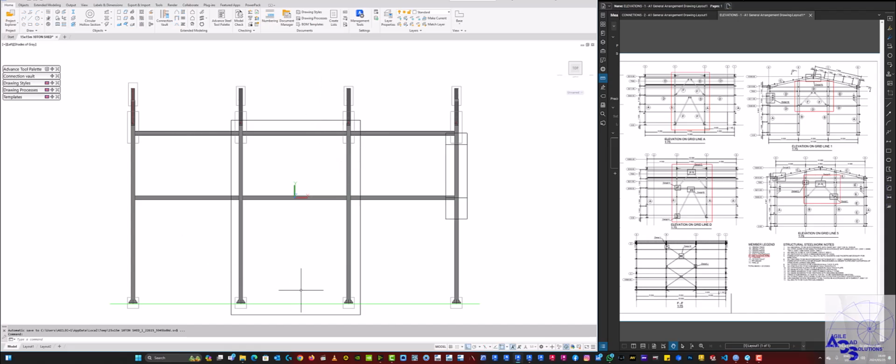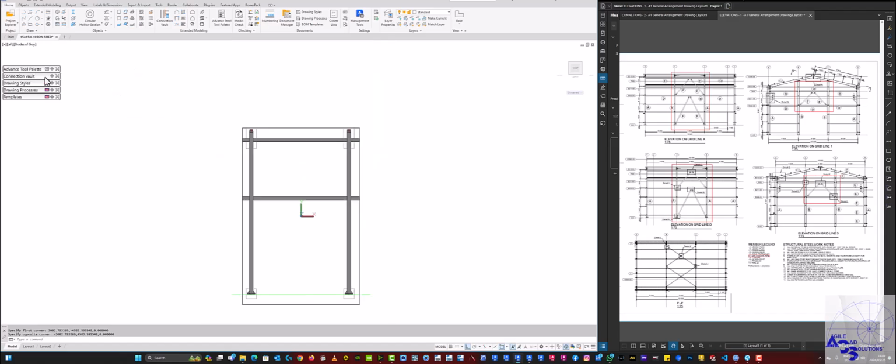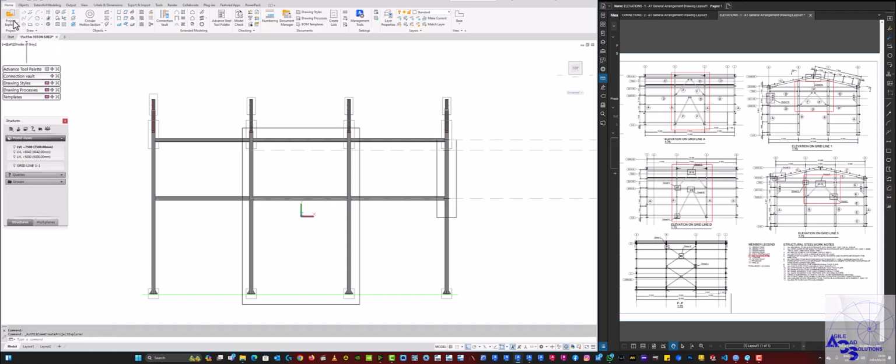So how do I then only see my elements within the box? You double click the box. That's the first option. Or what you can do is, let's just put everything back. All right, you go to Project Explorer. As you can see, in our model views, we only had levels before, but now we've got another model view, which is grid line 1-1.